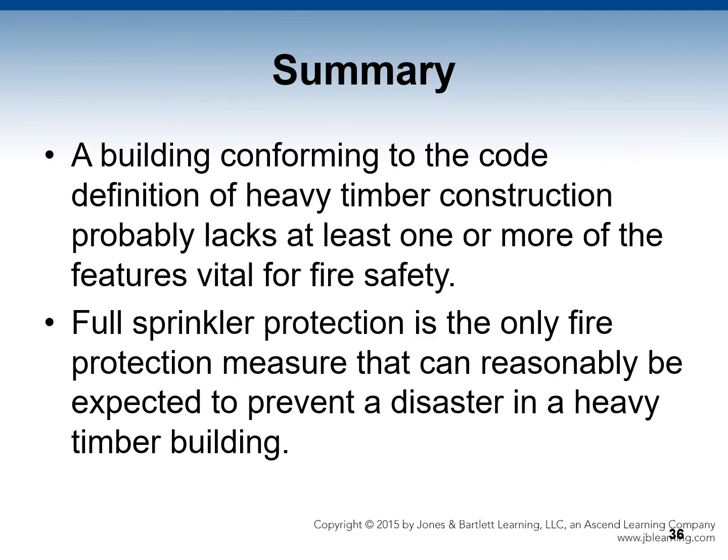A building conforming to the code definition of heavy timber construction probably lacks at least two or more of the features of the mill construction designers had learned were vital for fire safety. Of particular note are ceilings placed directly under beams, creating dangerous concealed spaces for fire spread. Full sprinkler protection adequately maintained is the only fire protection measure that can reasonably expect to prevent a disaster in